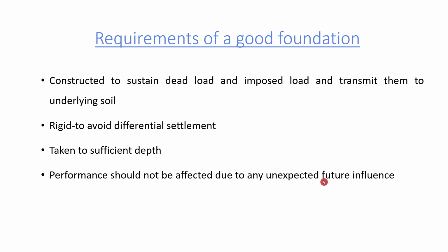We'll see the requirements of a good foundation. They are constructed to sustain dead load and imposed load and to transmit them to the underlying soil. So dead load, imposed load. Dead load is the load which is constant. That means the building weight all comes under the dead load. Imposed load or live load, they are the varying load, like the furniture load.